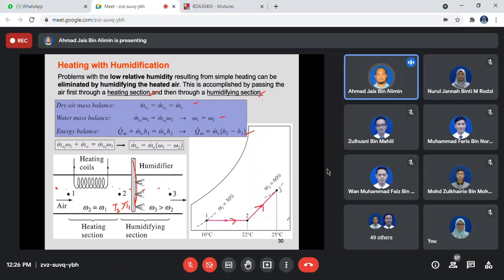Okay, so you have a different value here. This is the difference in terms of specific humidity. So this is specific humidity at 3, specific humidity at 2 is here. So this is how you sketch. You move from the left to the right and upwards to represent it. Going upwards means that you are increasing the humidity inside the area.